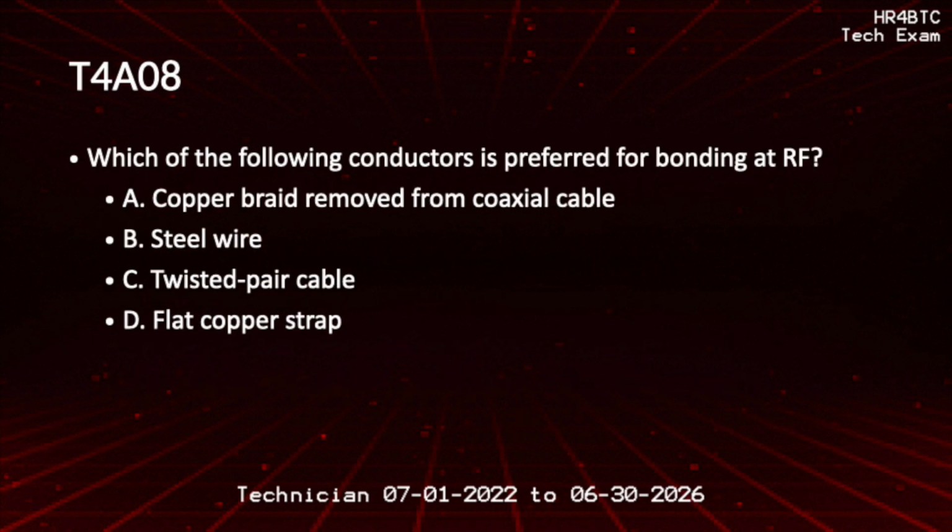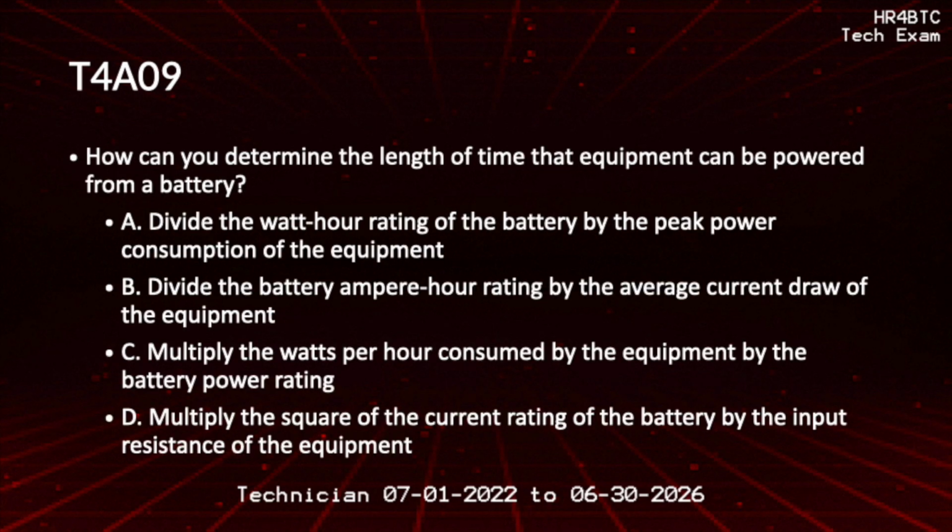Which of the following conductors is preferred for bonding at RF? Flat copper strap. How can you determine the length of time that equipment can be powered from a battery? Divide the battery ampere-hour rating by the average current draw of the equipment.